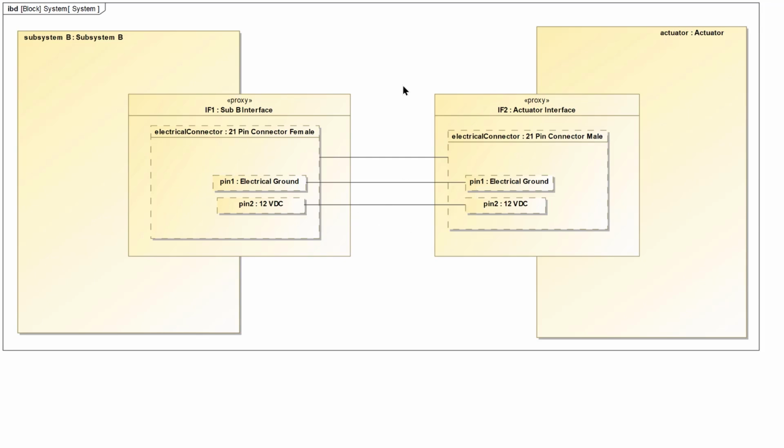And if you were to simply create an out-of-the-box Whitebox ICD that Cameo has available, what they do is they bury some of the script that actually parses out each side of this, which creates one column that shows one side of that and another column that shows what's in the other side of that. So if you were to try to recreate that on your own in a generic table, what you would find is that if you simply query that connector and then the ends, you'll get both ends in one column, and you don't get that mirrored side of that, so to speak, to see what connects to what. You'll actually have both results in one column, which is not typically what you'd like to see in a Whitebox ICD.